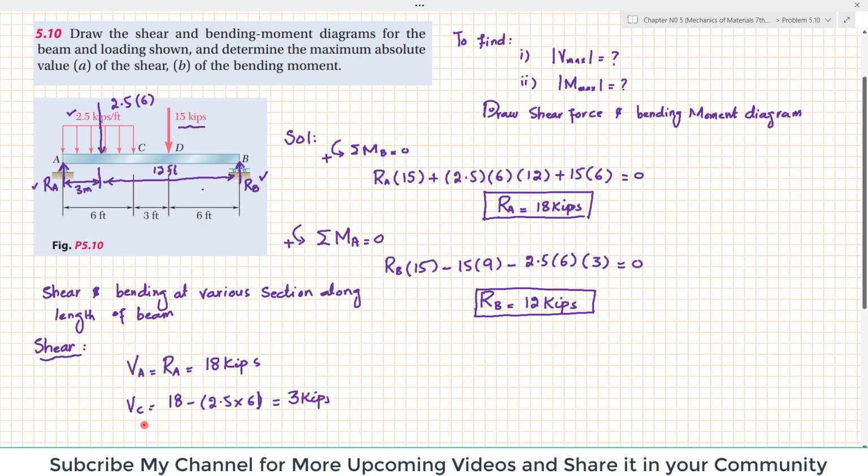Now from C to D, when you move from C to D, at point C we have 3 kips. So from C to D, the shear force will be equal to 3 kips, because you can see there is no load in between C and D. So the shear force will be this 3 kips.